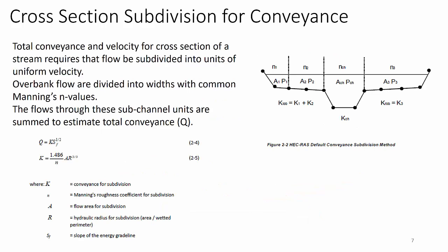We also understand that the flow through the channel, especially out of bank, is dominated by characteristics of the channel itself. And those cross sections for conveyance are absolutely critical for predicting velocities in the various sections of the river. Those velocities will differ based upon the resistance. You do not have uniform velocity across this system, and anyone who has watched a river from the banks, especially at flood stage, has seen this. You've seen slow eddying waters up near the out-of-bank pools, and then in the main channel you see the currents ripping through.